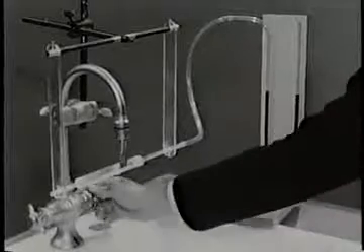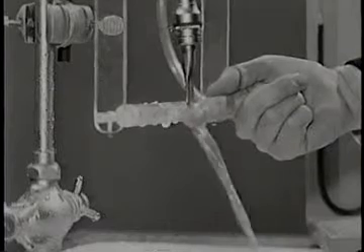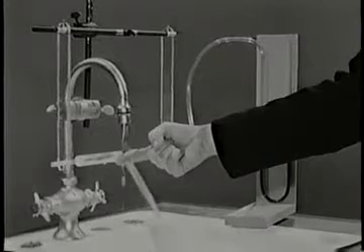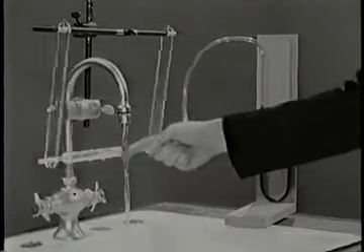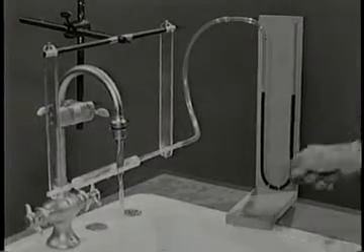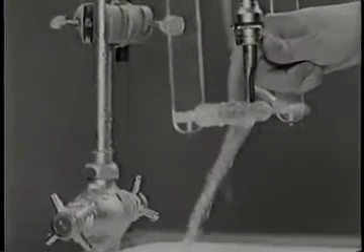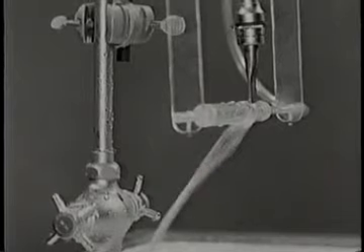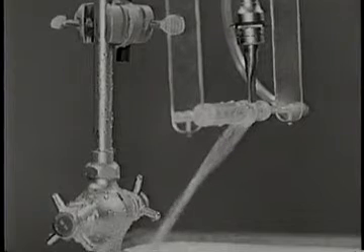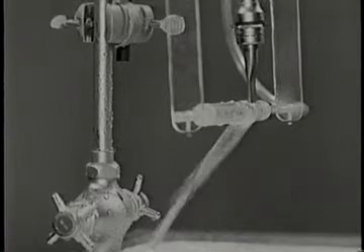This bending of the jet toward my finger is the Coanda effect. A better experimental setup is this freely suspended hollow cylinder with a small static pressure hole connected to a manometer. Since the streamlines are curved, there must be a normal pressure gradient, with the pressure at the cylinder surface less than the atmospheric pressure at the outside boundary of the jet. The manometer shows that the pressure is less than atmospheric.